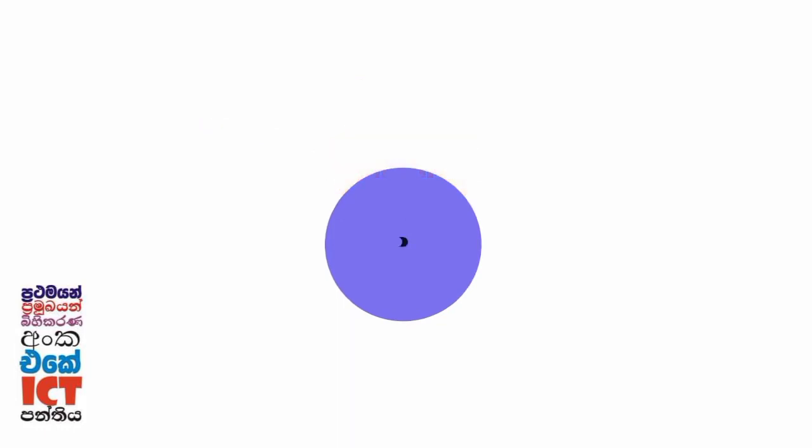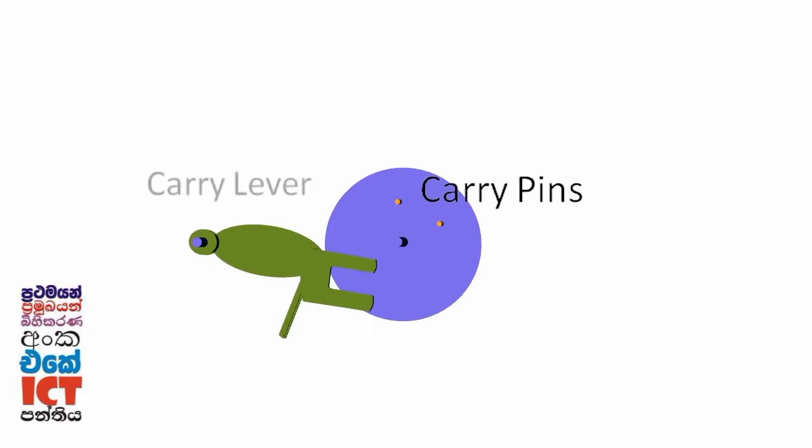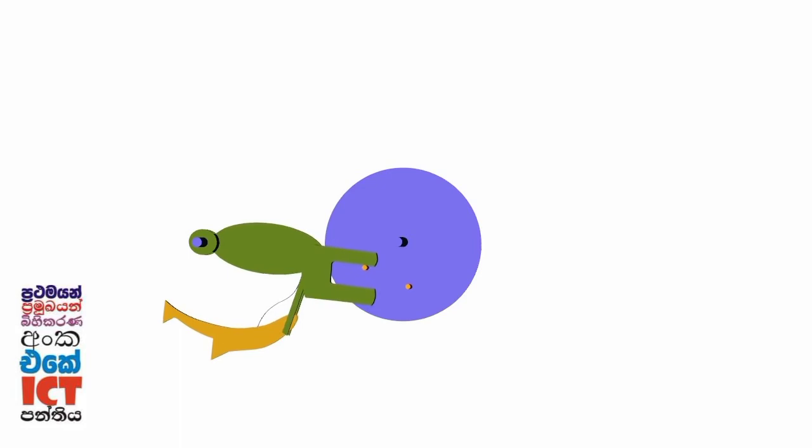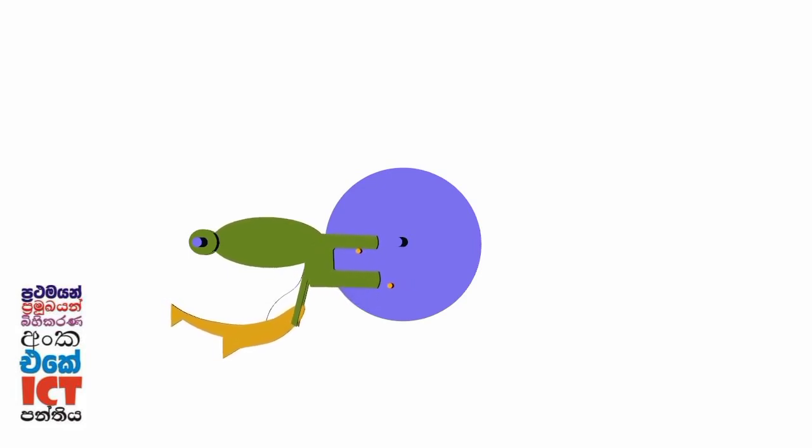The carry mechanism consists of two pins mounted on the back of the accumulator, a heavily weighted lever mounted on the axle of the accumulator belonging to the next higher order digit, and a spring-loaded pawl. The two pins are located in such a way as to engage a fork on the carry lever and lift it upwards as the accumulator advances towards the value 9.